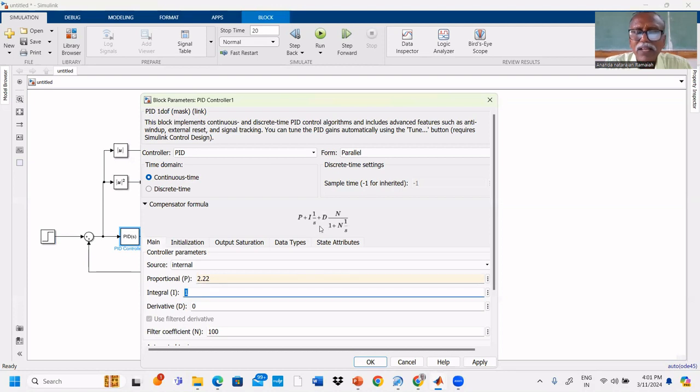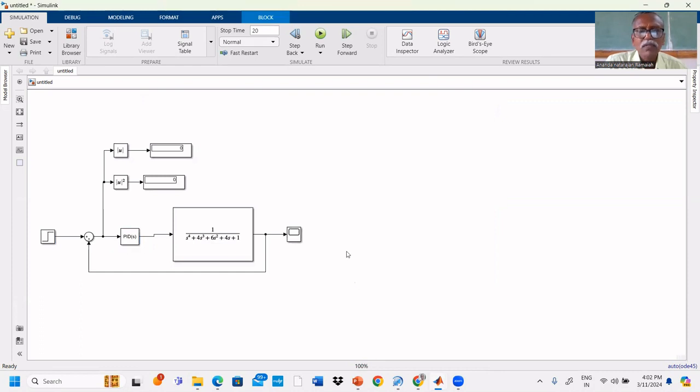And here you have to see the formula. In PID, everything is in the numerator, that's why we can substitute 0. Sometimes if it is Kc by Ti, you should not enter Ti equal to 0. So here we can enter 0 because it is I only. D also we can enter 0. That's all, so we entered P only controller.